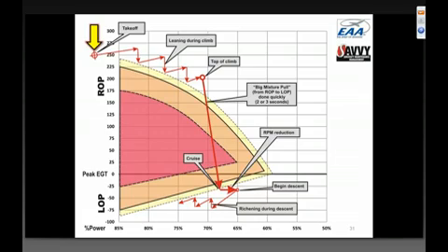So we start off at takeoff with a full rich mixture, which is a very rich mixture, something like 250 degrees rich of peak. And then as we climb, we should be gradually leaning the mixture because the mixture will automatically get richer and richer as we climb unless we do something about it. As you can see, the arrows kind of slope up, and then every 1,000 feet or 2,000 feet we pull back the red knob a little bit to keep the mixture in a reasonable place.